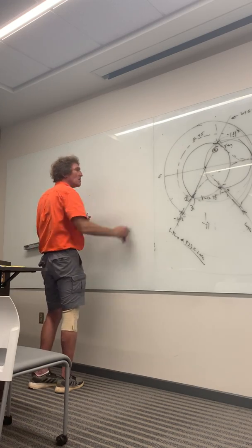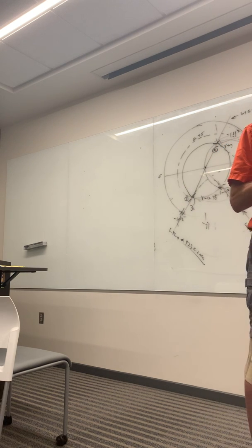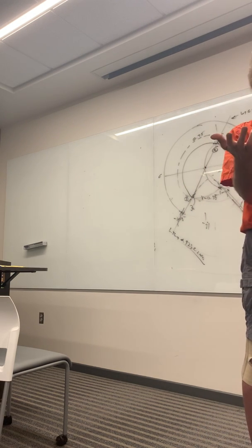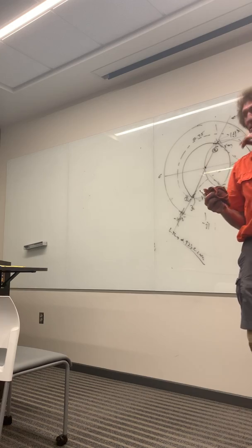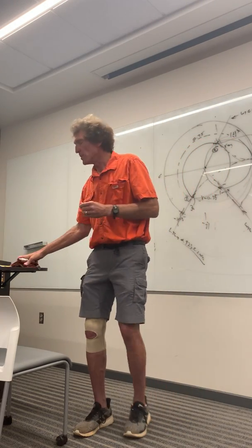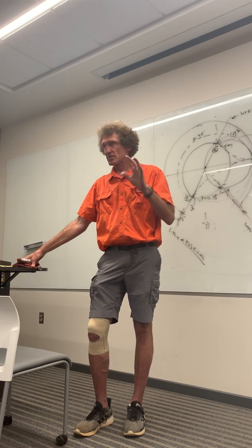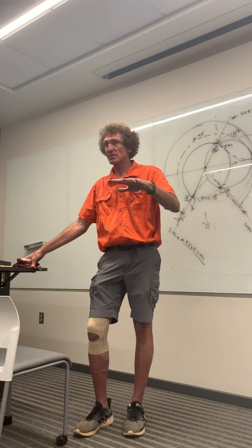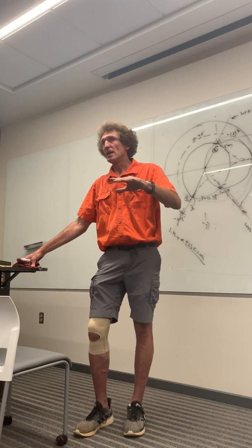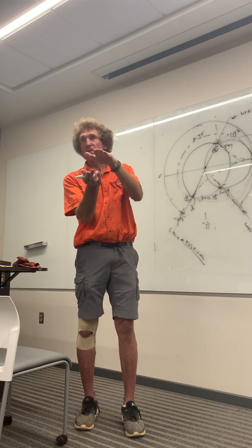And here's the thing. Most of the transmission lines we deal with are not coax cables. They're really microstrips on circuit boards. Have you all seen Duroid board or anything like that? Do you know what I'm talking about? A lot of the stuff you do as electrical engineers has to do with either very large scale integrated circuit designs or board designs. Do you know what FR4 board is, the green stuff? Or Duroid board? These are simply a piece of copper, an insulator, another piece of copper.